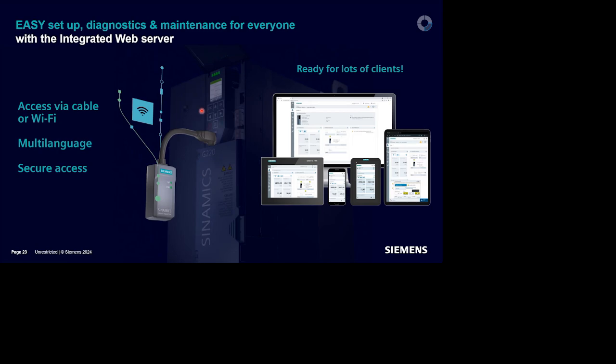So how do we access this integrated web server, which is located at the front, as you see, at the bottom of the operator panel? We can access either via cable, directly with a patch cable. You can even access via this OTG cable. From one side, you can connect an RJ45, and from the other side, you can connect it to your phone directly. Or you can also access via Wi-Fi.